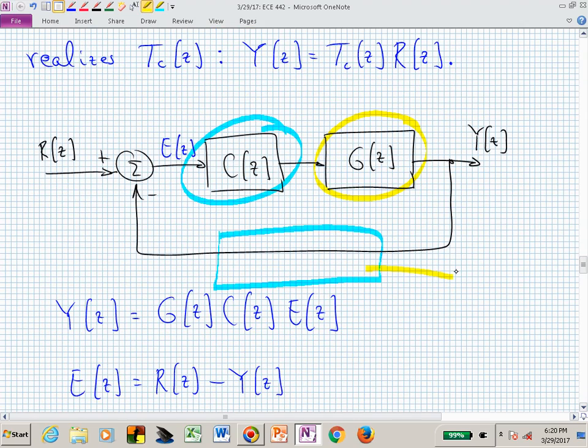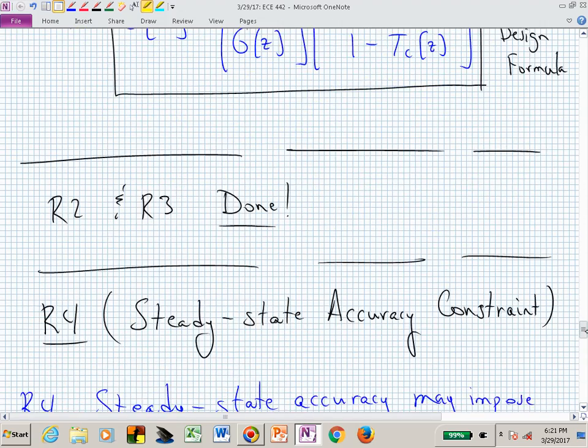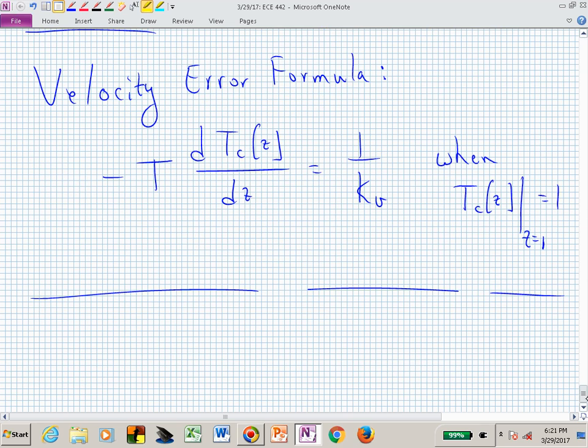It's just that that would make the formulas a little bit more complicated, and that doesn't really change the thought process or the strategy. But yes, it could be done, but in fact, we have restricted this design to be utilized when we have a 1 in that feedback path. And that's what we'll assume if we are doing the Ragazzini design. We're assuming that closed loop control structure. Does that answer your question?